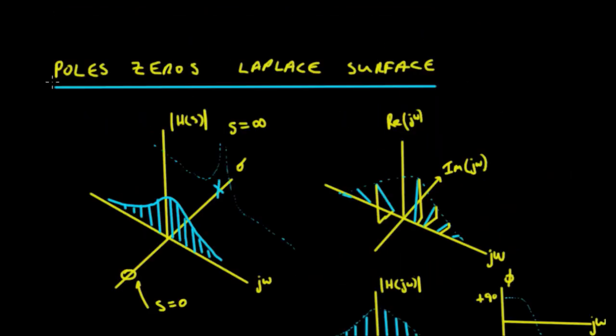Now the last little bit is to look at poles and zeros. If we had the complex frequency domain, we would have a sigma and a j omega here, and if we were to have a pole, say somewhere up on this sigma axis, this would force this plane up to infinity at this point. If we think about this in terms of some elastic surface, then if we move down the sigma axis until sigma gets to 0, we'll be on purely our frequency axis. In that case we would have a raised section here, which in effect would be our low pass filter.